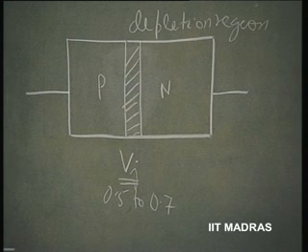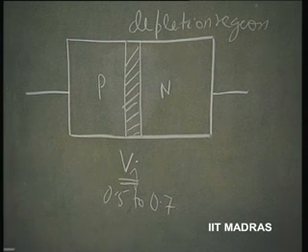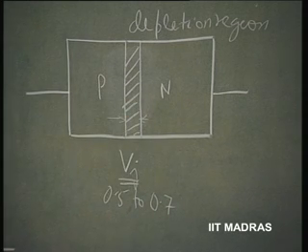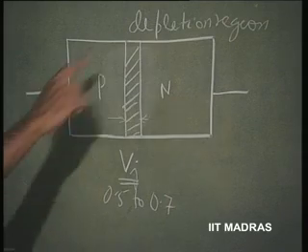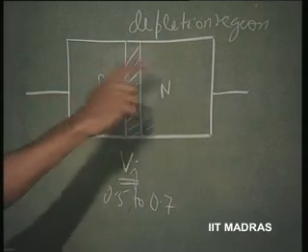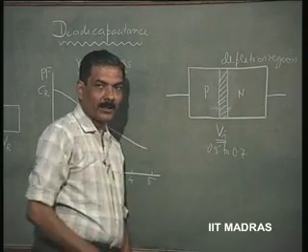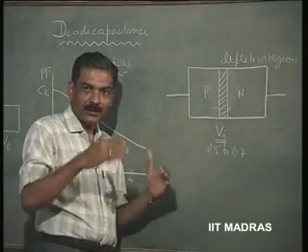So, this region where it is depleted of carriers is called the depletion region. Every p-n junction has a depletion region in between, and this depletion region width is dependent upon the voltage. When the junction gets forward biased, the barrier, the potential hill for these carriers, decreases. So, there is a copious amount of free carriers moving, holes moving from this side to this and electrons moving to this, and that constitutes a current; large current can flow.